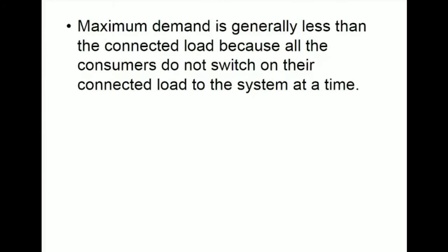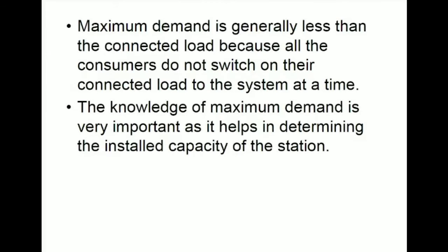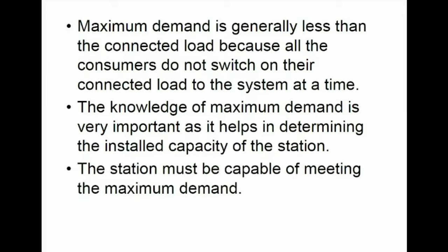Maximum demand is generally less than the total connected load because all the consumers do not switch on their connected load to the system at a time. The knowledge of maximum demand is very important as it helps in determining the installed capacity of the station. The station must be capable of meeting the maximum demand at any time.